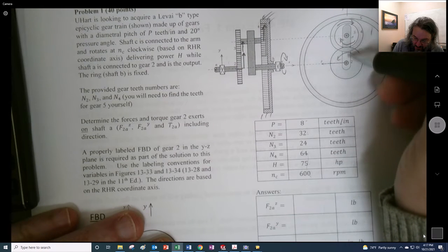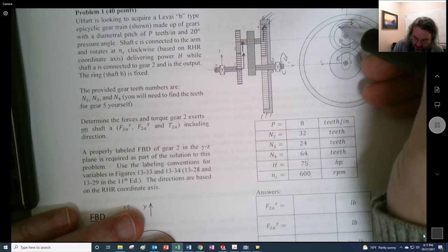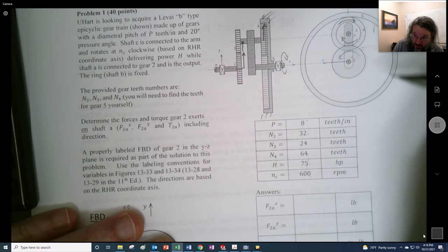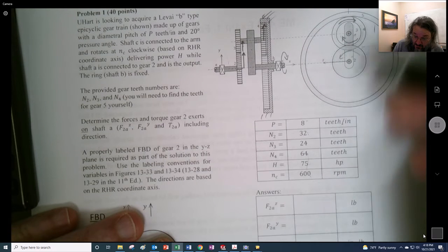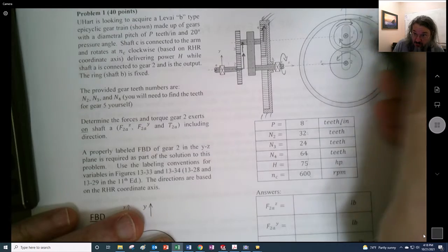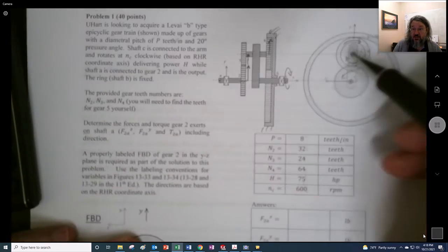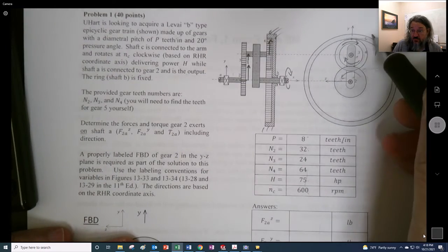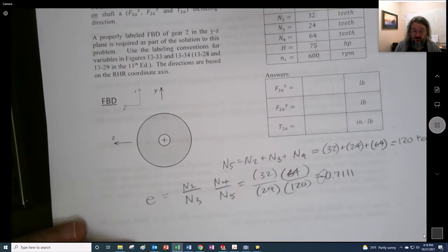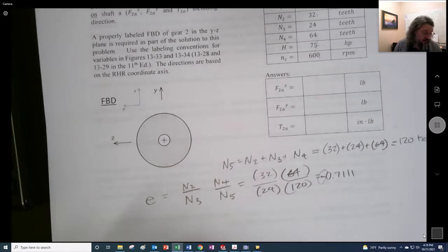But now, if I'm holding this arm in place, and 4 goes clockwise, 5 will go clockwise as well, right? Because it has to, because these 2 points right here have to share the same velocity. So that means counterclockwise in, clockwise out. This must be negative. And that will affect our answer later, because we need to get the equation.